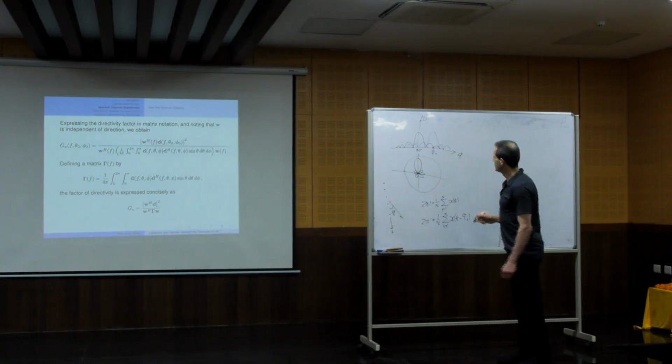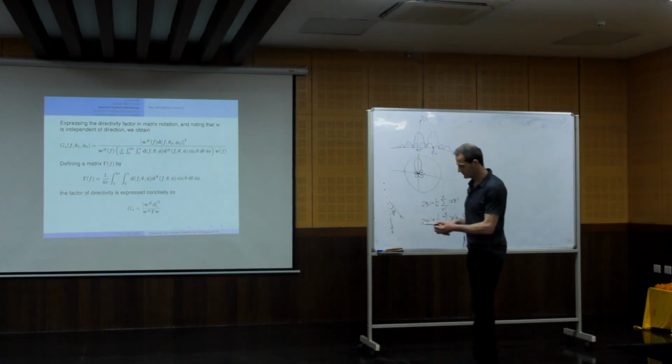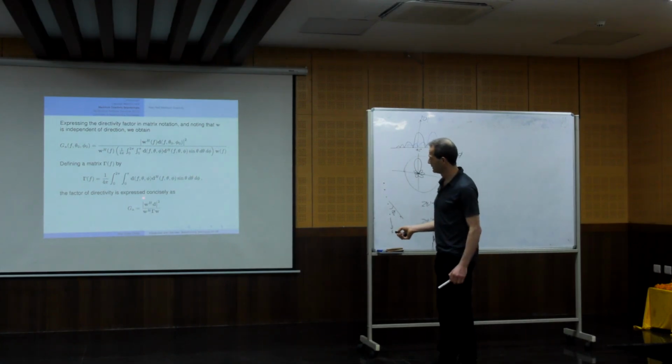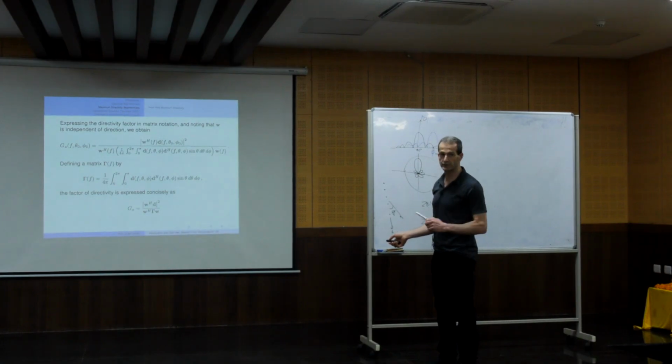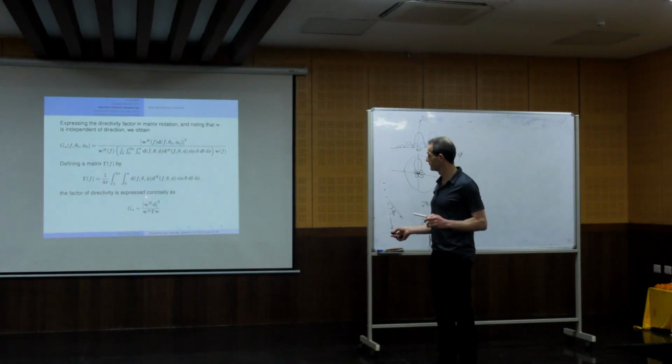So in this directivity, the numerator is the gain for the desired source, and the denominator is the gain for diffuse noise. We want to maximize this ratio for each frequency. We can do it independently for each frequency.